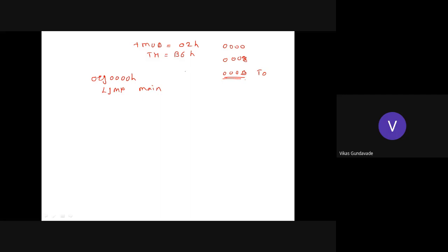Okay, so here we will jump here. Now, here we will write the ISR of the timer 0. So we need to again initiate the location at 000B. After initiating that location, we will complement port pin, port 1.1, I think. This is port 1.1, right? So here we will complement port 1.1, and after that we will return from the main program.